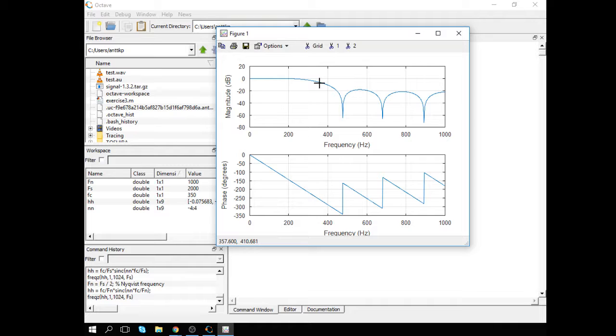The only bad thing is that this isn't much better than any running average filter because the stop band attenuation is not that great, only 20 dB. We can do much better stop band attenuation with the same number of parameters.